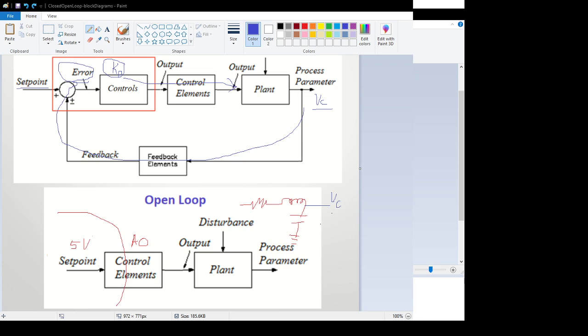All right, and I'm going to use ladder logic then to select them using these selector contacts on my selector switch. Okay. And my set point, right now I've got set to 5. Okay, so here is my logic.